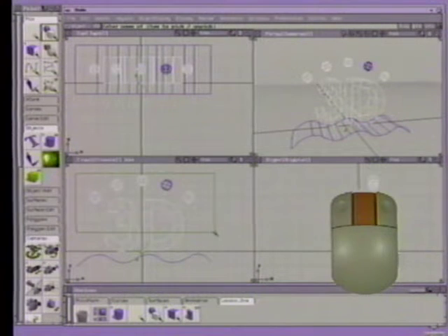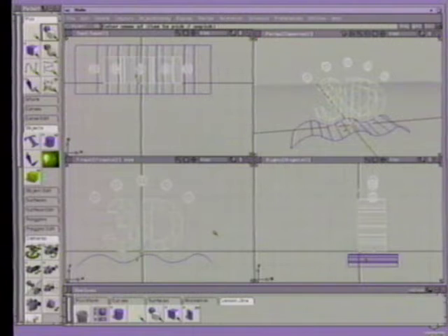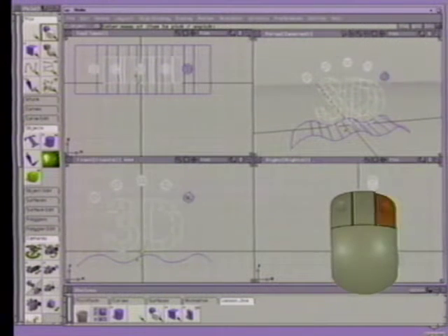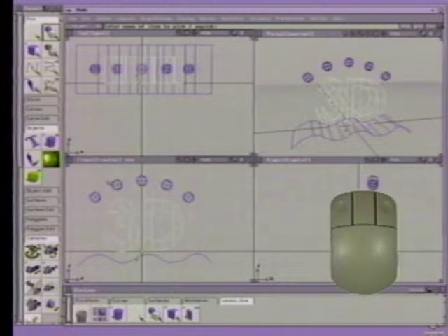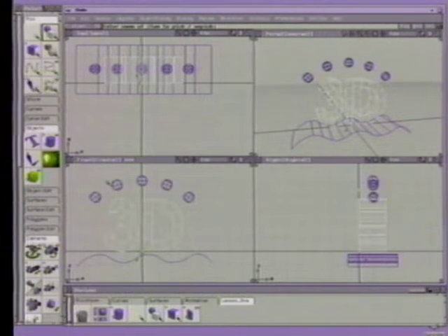Next, click-drag a pick box with the middle mouse button around the 5 spheres and the 3D text. All the objects are now picked. The difference between these picks is evident because the middle button replaces the old selection while the left mouse button toggles it. Next, click on the 5 spheres individually with the right mouse button. They are removed from the pick set.